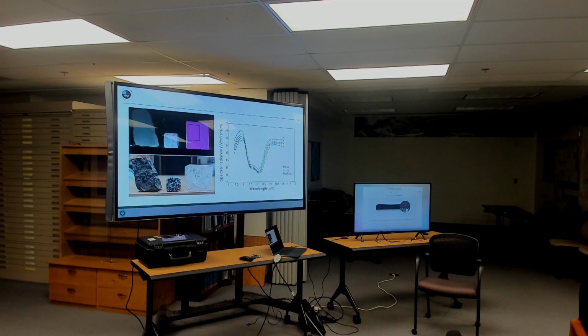Watch what happens when I turn. Right. So the temperature of that side, the brightness temperature is closer to 20 degrees. Right. On the blackened side, that's like 75 degrees, right? I'll turn it around and show it this side, which is just aluminum, right? Kind of scuffed up aluminum. Then the brightness temperature is way down at 20 degrees, right? With a couple of these spots, which are much higher.